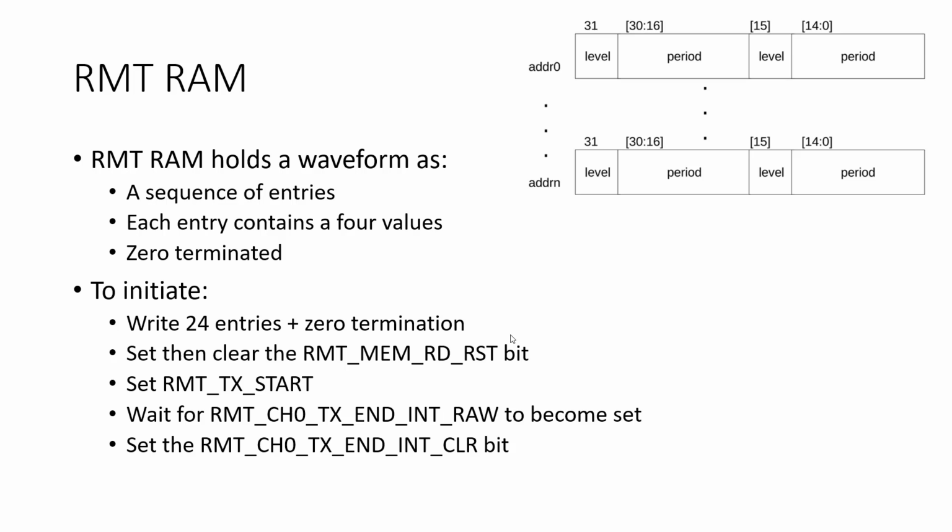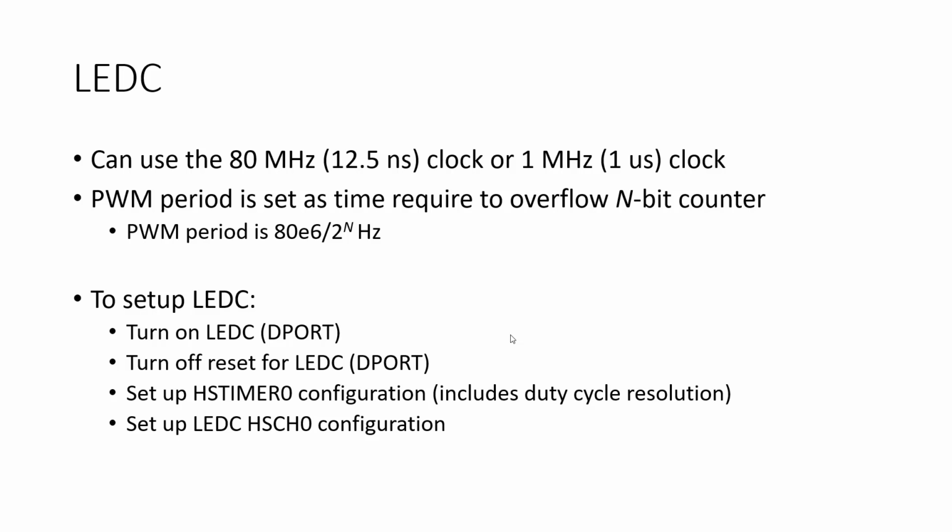Yeah, this is polling. That's a good point. It's called an interrupt, and we covered interrupts in this class, but it's a misnomer because you're basically saying, are you done yet? Are you done yet? That's polling, right? As opposed to, let me know when you're done. That's an interrupt. Okay, that's it for that. There's more details in the lab sheet. Oh, by the way, if you find any bugs in the lab sheet, let me know. We've been through several revisions of it, but this is the first time we used it.